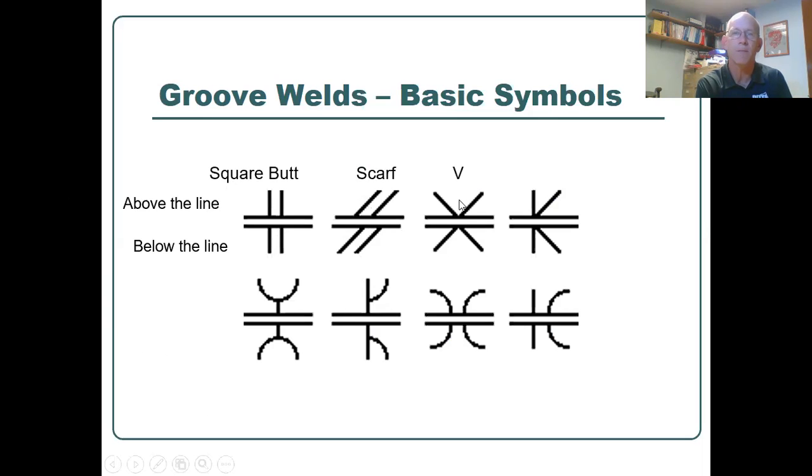You do see a lot of these, boy, a V-weld, that's really easy. This one is not a K-weld, this is a bevel. And a bevel is another one that's really, really common because it's really easy to cut an angle on one side, and that's all this is. On the V-groove, we've beveled or cut an angle, ground an angle, or torched it on both sides of the metal that we're butting up.